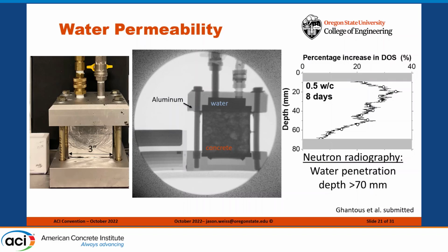This happens to be hydraulic permeability. So the common test here is you push water into a sample, crack the sample open and see how far the water went. The visual technique gives you a measure of how far the water went to get to 78% saturation. No one ever says 78% saturation. They think it's full saturation, but where you can start to detect the visibility of water is around 78%.